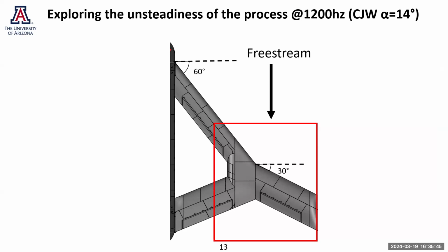So in here, what we looked at was a different wing with similar geometry. We selected this wing because it is almost the same thickness as the earlier wing where the thickness varied along the span, and we had troubles with the laser reflection and everything. In here, we do not have those troubles. There is still a non-zero leading edge radius, so that does impact the leading edge vortex development. Also, as you can see, there's a big hole in the middle, so that does influence how the flow behaves as well.